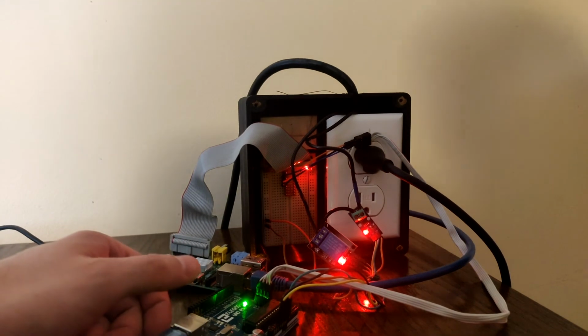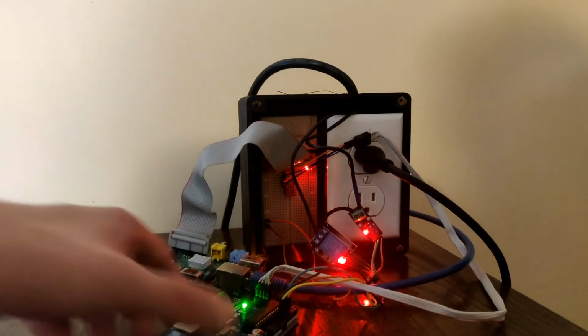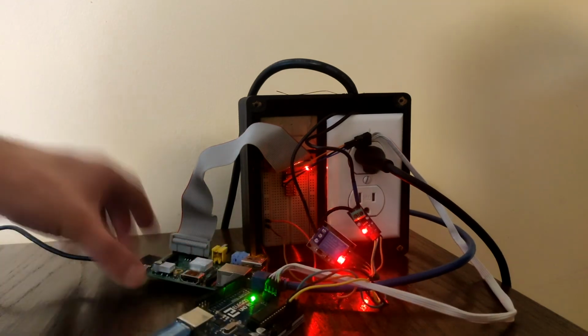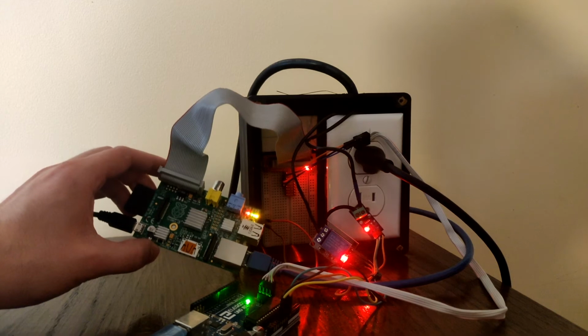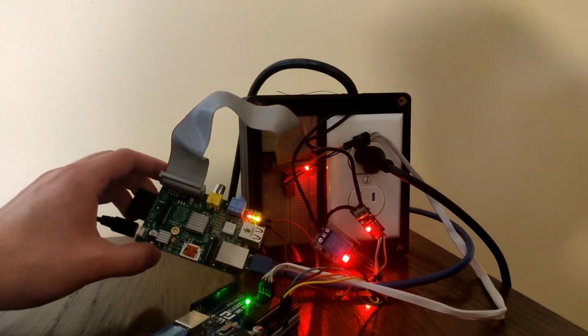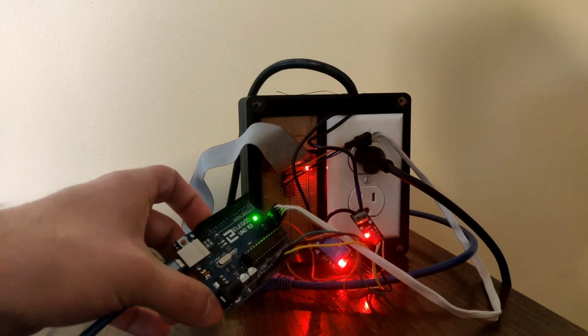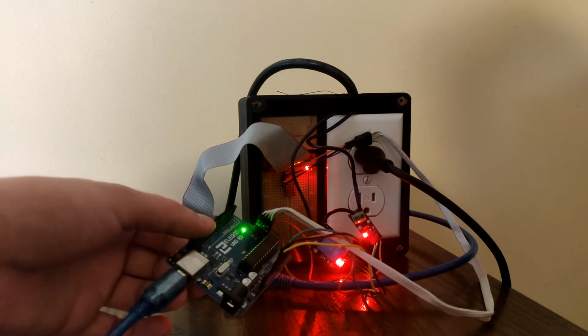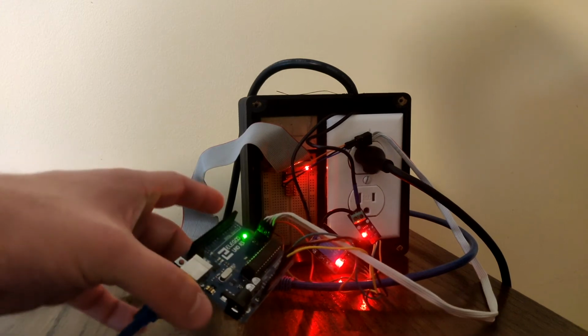And the reason why we're not able to use the Raspberry Pi directly and why we have to use an Arduino Uno as well is because the Raspberry Pi here does not support analog input. It only supports digital. So we have to use this pretty much as an analog-to-digital converter for the Raspberry Pi, which we could replace with an integrated circuit that would also do the same job.